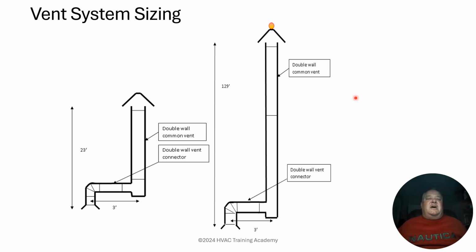A little earlier, I talked about interpolation and extrapolation. And again, I said I wanted to explain that. I'm going to do that now before I forget. Interpolation is going to be, so if I said on our vent table, it says that we can have a capacity, and again, I'm making up numbers here. At 20 feet, it might say we have a capacity of 40,000 BTUs. At 25 feet, again, making up a number, it could say that we have a capacity of 45,000 BTUs. So at 20, we had 40. At 25, we have 45.